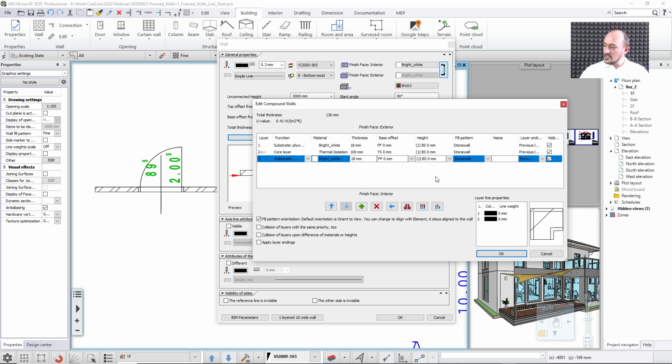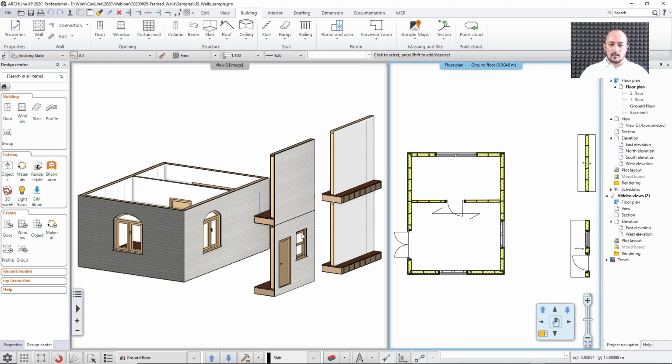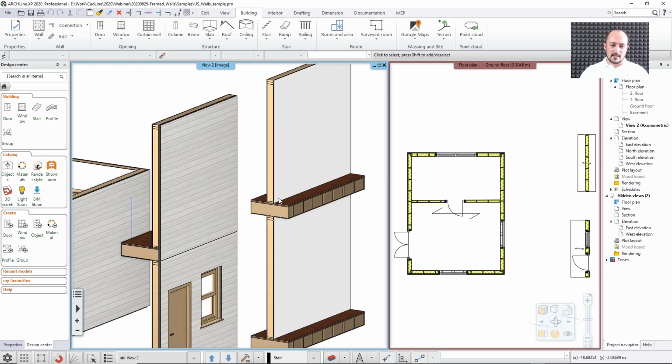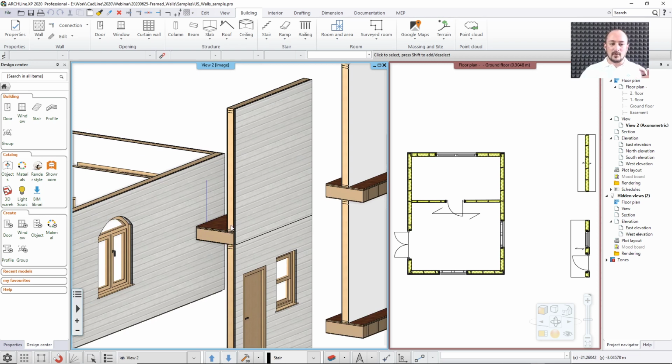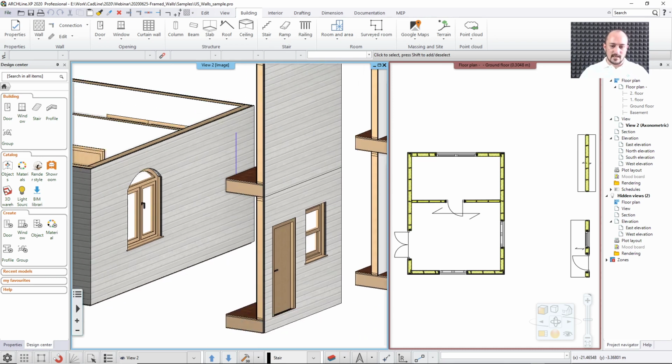The reason I'm doing this is actually represented in another example. Let me just load that up. This is an example of an American structure. And what I'm going to do is this. I create those connections by telling the software that I'm going to rest this framing system on top of the load-bearing beams, that is the top of the structure, and then I will just land these other layers, in case of this partition wall, on top of the finished floor, wherever it should be on that specific level. It will automatically connect to the proper place.